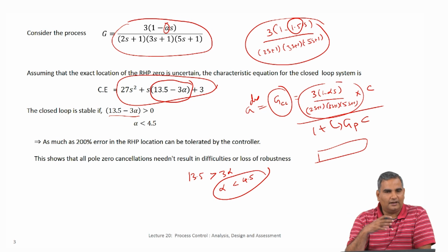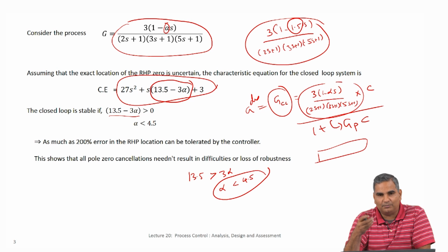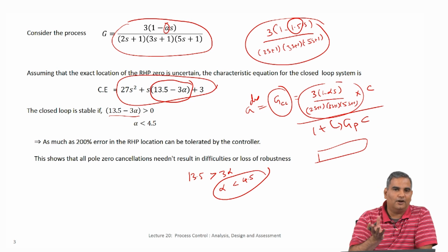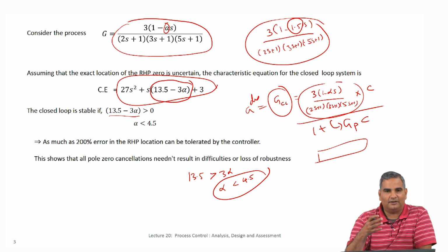In the other case also model parameters are very much there, but they get buried into your PID controller. Here it is more explicit, and as you go more and more advanced in control topics, it will become more and more explicit in the controller calculations themselves. Even here, though I say the controller is 1 over GM, and that is where the model explicitly comes in, ultimately we got a PID controller. So, all the parameters were used and the implementation is PID.